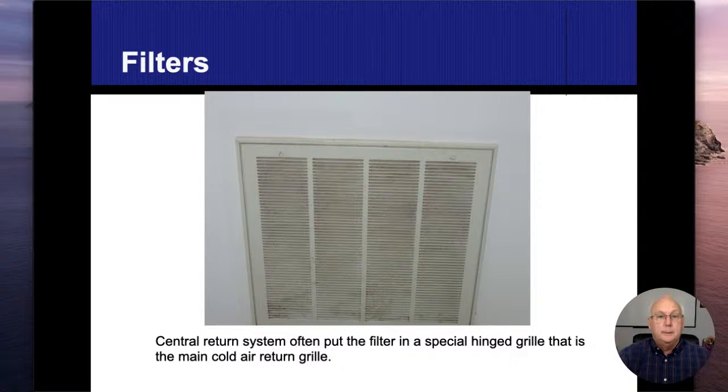Again, our filters, I can't stress enough to my clients the importance of keeping these air filters clean, keeping them changed. People always ask, how often should we do it? And to me, it depends on the filter. I know they have some of them that you could keep in there for a year, and they have other ones that you should be changing every 30 days. All right. I think it matters more so how much air you're flowing, how clean your house is, pets. There's a lot of other things that come into play. But the main purpose of these filters is to filter the air. But when they get dirty, they also restrict the airflow that comes across.